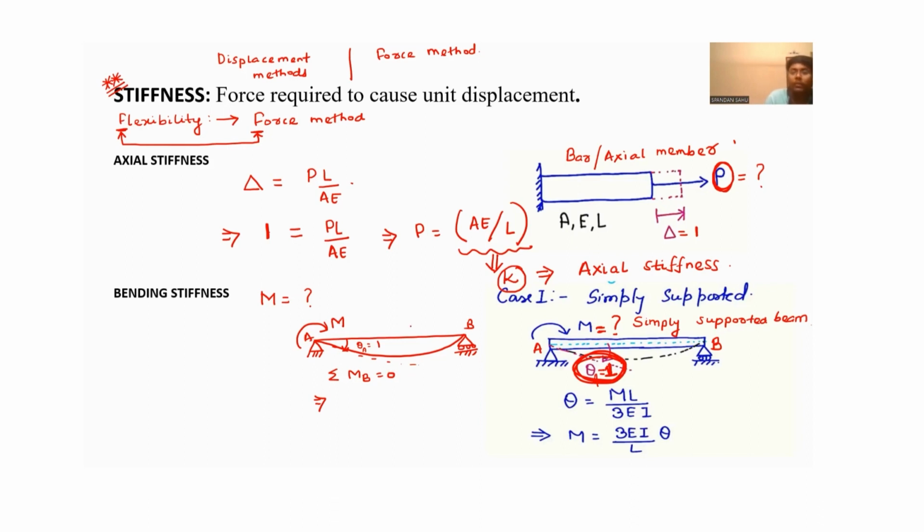Yes, because this is a beam and part of our civil structure, and we know that our structure is in the state of static equilibrium. Hence, the equations of static equilibrium, that is summation of Fx equal to 0, summation of Fy equal to 0, and summation of moment about the out of plane direction equal to 0, can be written.